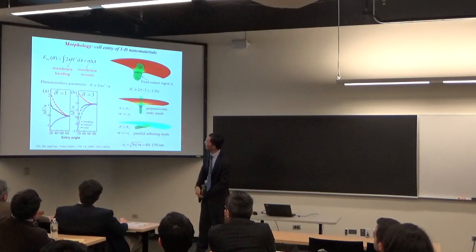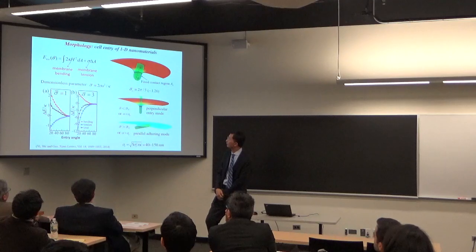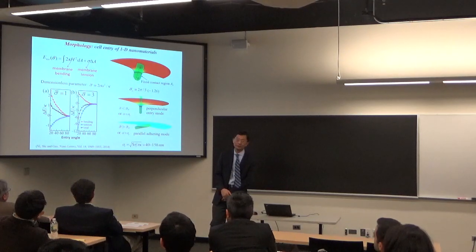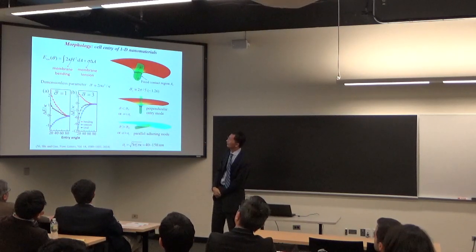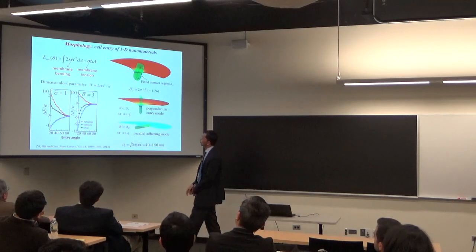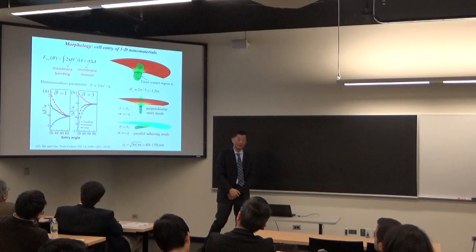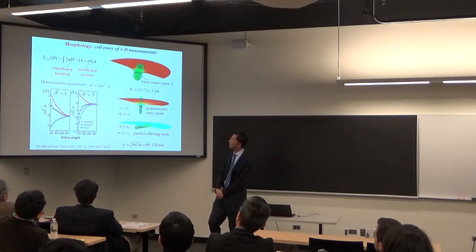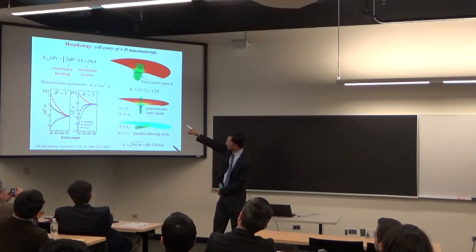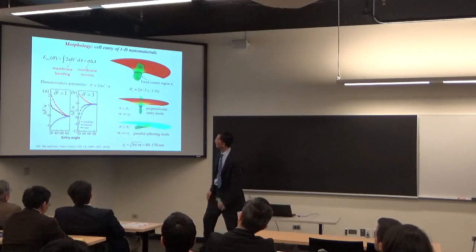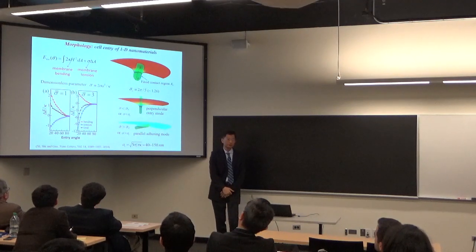The second term, sigma delta A, is the membrane tension energy. The membrane tension is also a known physical parameter. Delta A is the change in membrane surface area due to the insertion of the nanomaterial. So these two energies compete with each other to govern the uptake process. From that free energy, doing a dimensional analysis, there's only one non-dimensional parameter, sigma bar: 2 sigma, the membrane tension, scaled by the square of the radius of the fiber, divided by the bending rigidity.